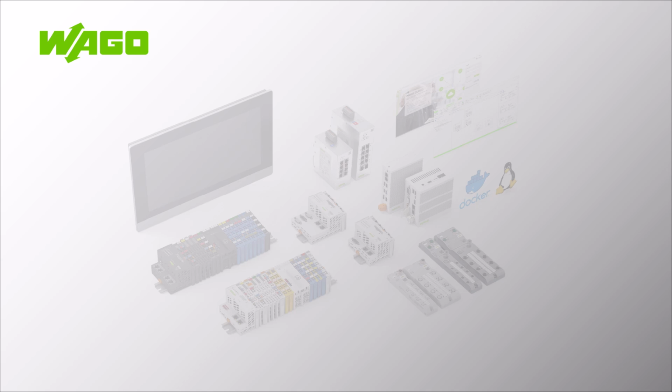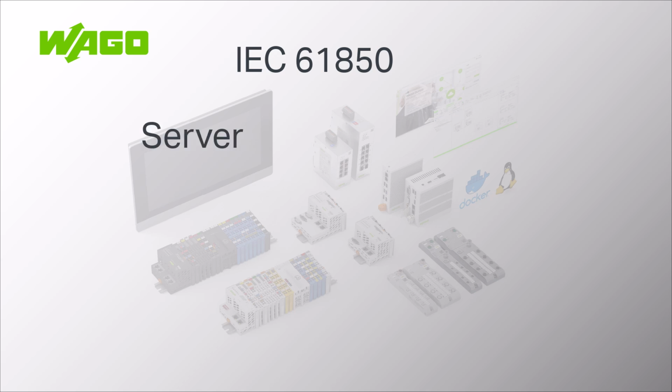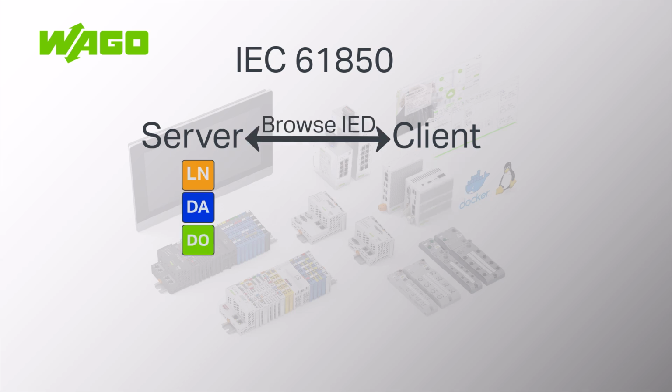Hello, and welcome to this WAGO tutorial where we'll guide you through configuring a server and client using the IEC61850 Telecontrol protocol. In the IEC61850 standard, data points are primarily created on the server and then transferred to the client. There are two methods for this: either export an SCL file with the data structure and import it into the client, or with some servers, the client can read the available data structure directly.